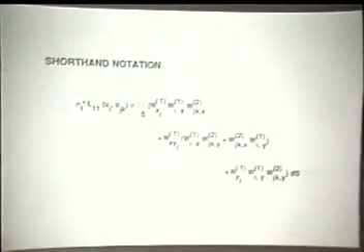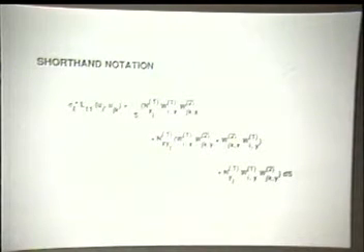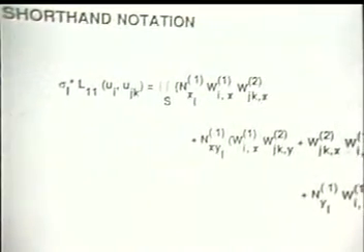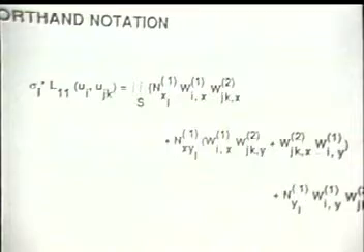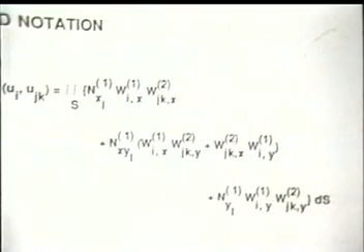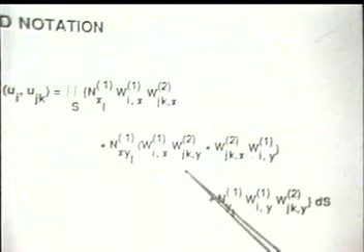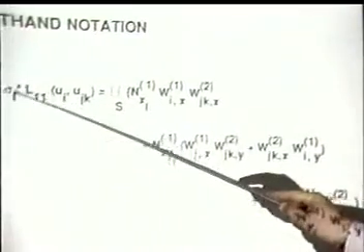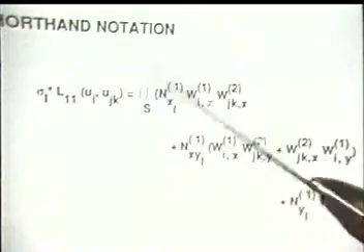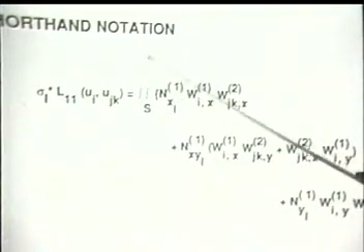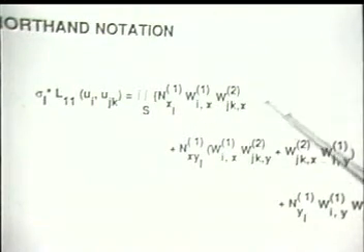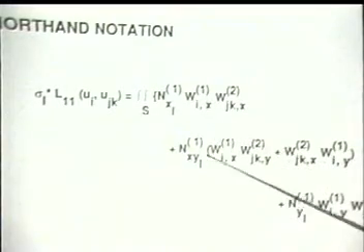Now, I will give you some detail what these coefficients look like. There will be rather elaborate formulas, and in order to be able to get them on a slide, I will have to use a shorthand notation. The shorthand notation was once again introduced by Frauenthal and Hutchinson in their paper. And if you look at it, I will use a symbol that looks like this: sigma star, L11, and two arguments. What does that mean? That stands for a surface integral over the mid-surface of the shell, and it always involves a product of three terms.